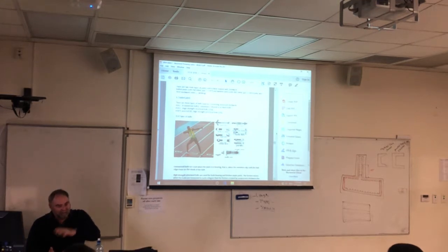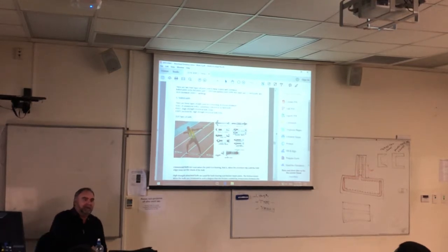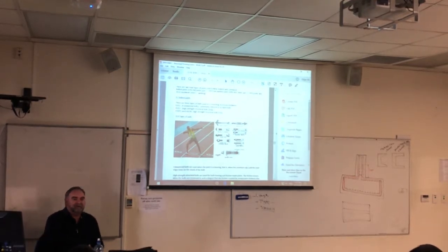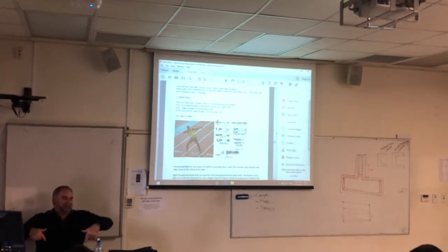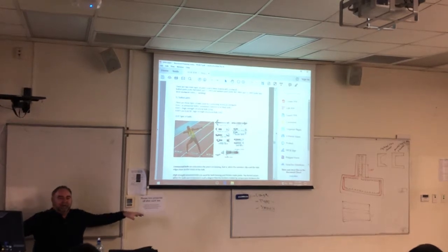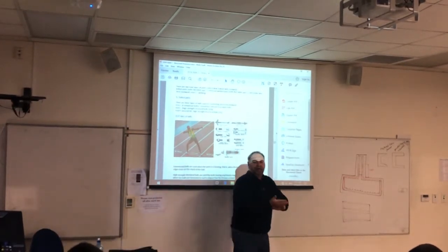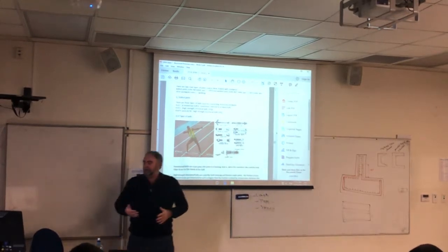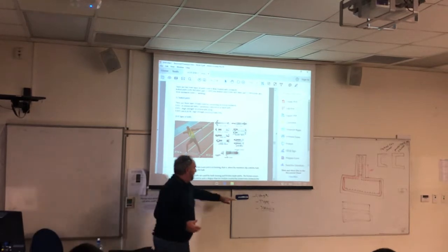So you can get the boards really tightly fitting, but you want to recess it so that somebody walking along isn't going to trip on the bolt, especially a student running off to play volleyball with bare feet or jandals on. On the handrail, the last thing you want is to be cutting your fingers every time you walk along the bridge. So you've got to think of the type of bolt which is best to go on. So that's the type of bolt.